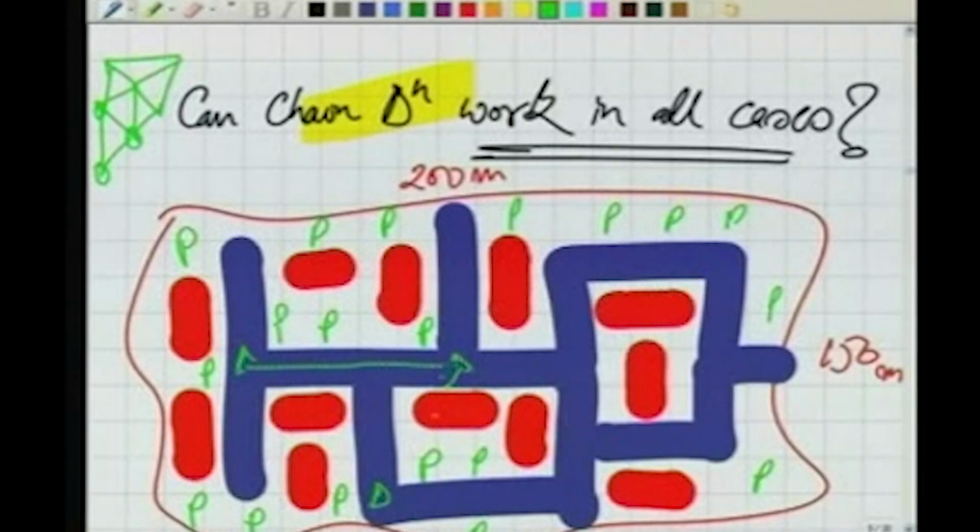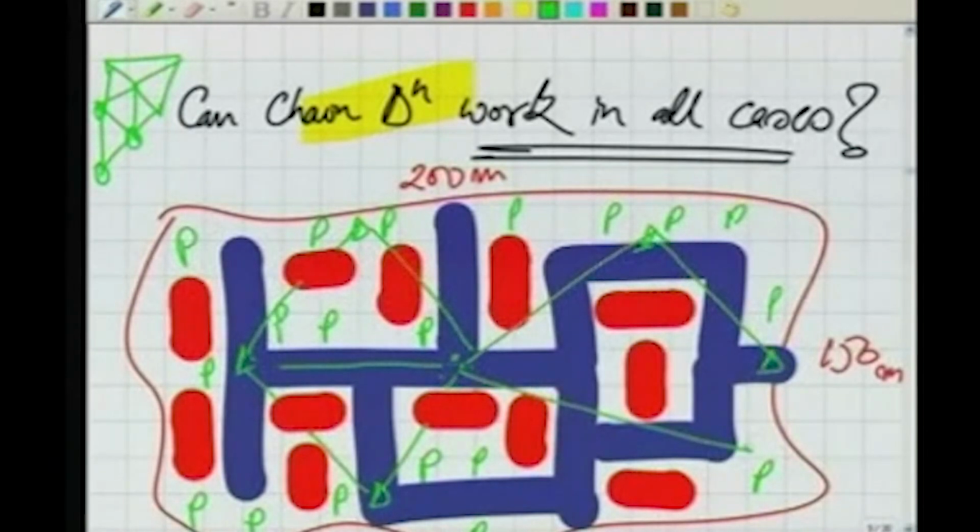Can I take the third here? I cannot, because this building is obstructing the line of sight. Here also it is obstructing the line of sight. Here also. I cannot take anything here. So making a net of triangles in this figure is really difficult. I can go for a line here, maybe another one here, but it's not a triangle. If I want to make a triangle using this line, I cannot, neither this, because the lines of sight are obstructed by these buildings.